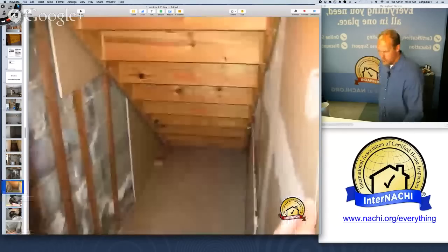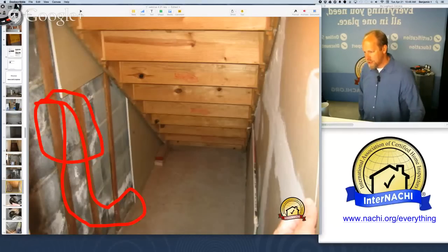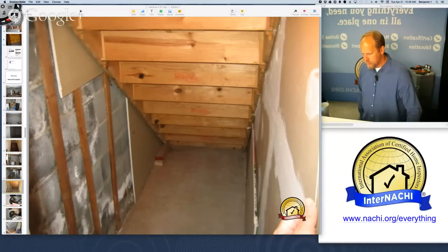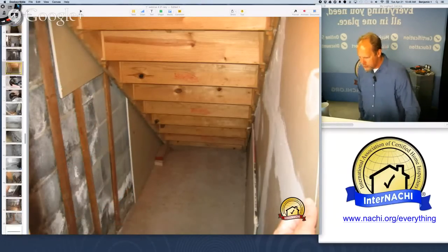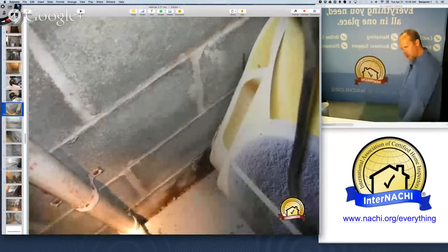On the basement walls, you can see efflorescence. So I see a lot of efflorescence. Efflorescence is salt deposits left behind when water interacts with masonry units. So that's an indication of moisture coming in. So I've got water coming in, I've got watermarks.